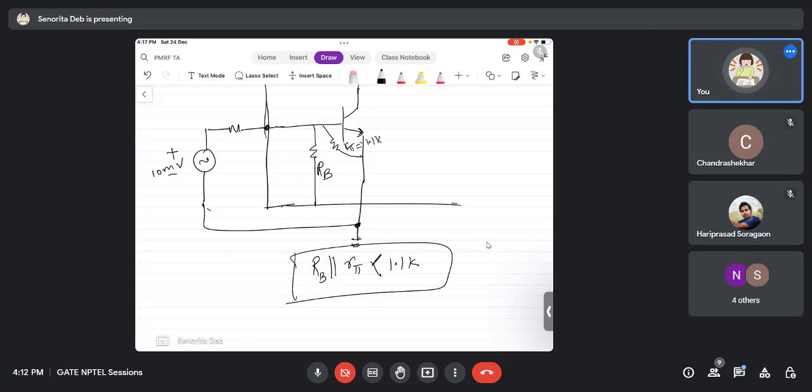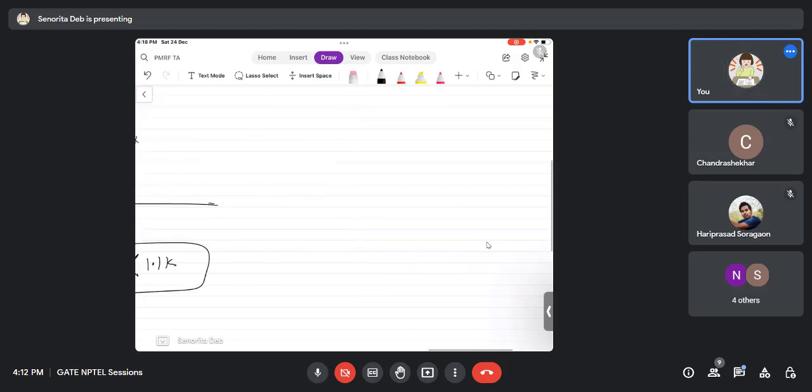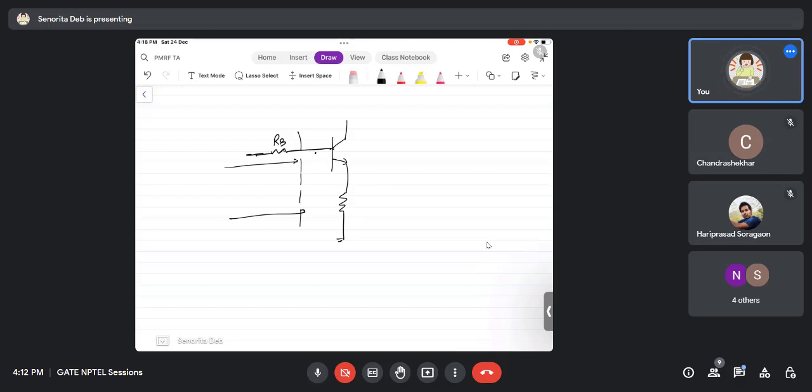There is one more method through which we increase the input impedance, and that is the presence of an emitter resistance. Remember, this RB resistance here is for the DC biasing. It has nothing to do with the input impedance, because the signal will always see what is in parallel to it. The series resistance only matters with the drop of the current, which is used for the DC biasing. What you see in parallel is what will matter. This is not what you should be worried about.